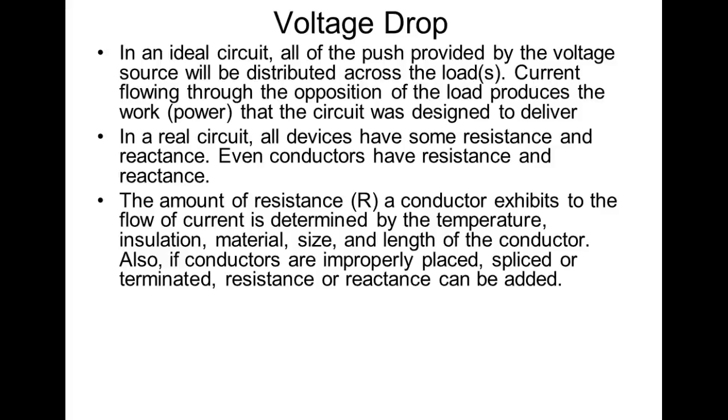All conductors that we're going to deal with have resistance. If I put current through resistance, we're going to have a voltage drop. If I have a voltage drop and I have current, then I have power. And resistance releases power in the form of heat. So conductors, real high current conductors, will get warm. This is why if you go into electrical classes, they'll talk about size of conductors, and we have to do certain things. So that's for a normal size house.